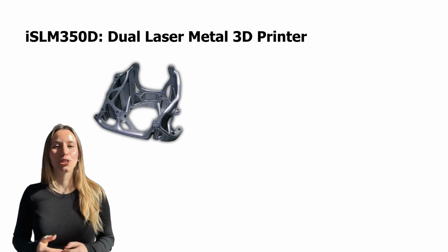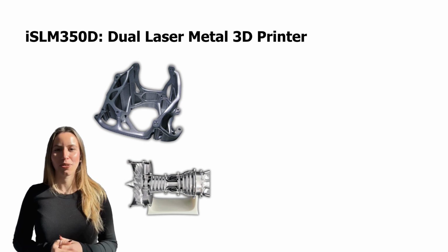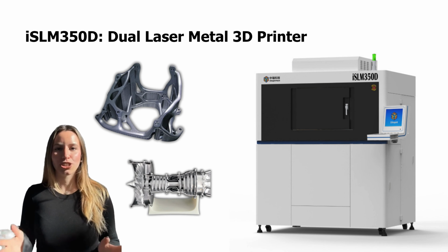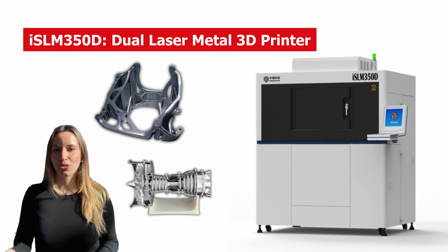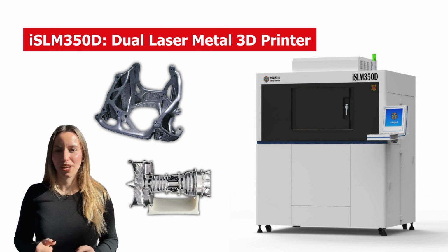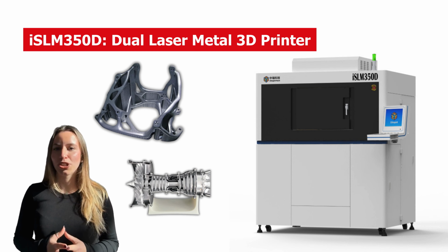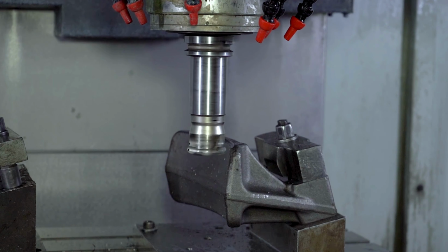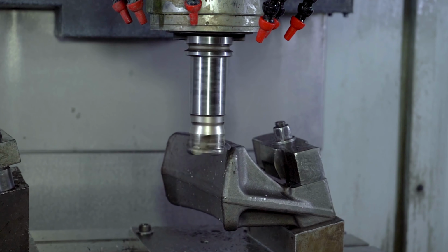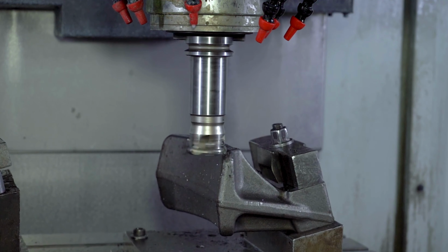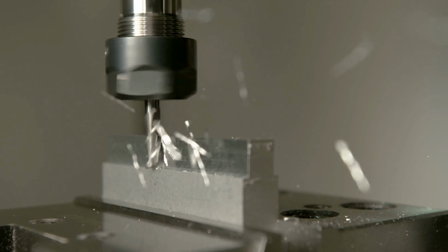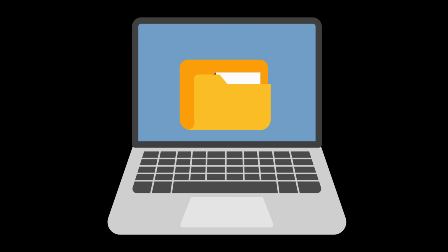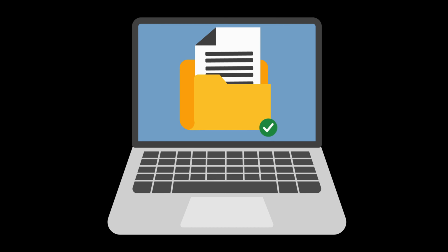At high volumes, traditional mass production methods still dominate, especially for simple parts. However, additive manufacturing is often used to support production during ramp-up phases, or when supply chain limitations make traditional production difficult. One of the largest hidden costs in manufacturing is tooling. Designing, producing, and maintaining molds and fixtures requires both time and capital. Additive manufacturing eliminates most of these costs by replacing physical tooling with digital files.